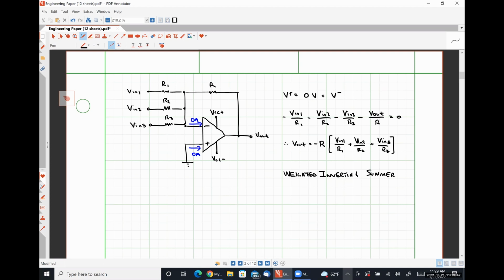You can set your weight conversion by your resistor values. You could literally use resistor values to give you your answer in kilograms, metric tons, imperial tons, whatever you wanted, all by choosing your resistor values specifically for however your load cell converts weight into an electrical signal. That's a classic example of an inverting summer.